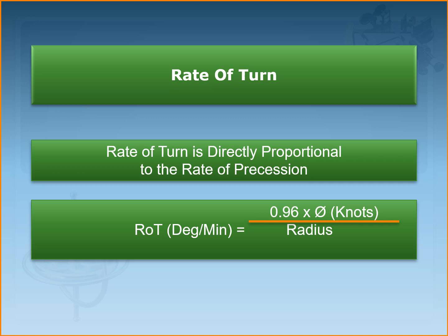This information is very useful when the vessel is maneuvering in narrow channels, or making alterations of broad or large value of courses, or making course alterations between two land masses. Here, knowing the rate of turn in degrees per minute is useful, especially as passage plan information. So you should be calculating this information and putting it down on your passage plans so that you can monitor the vessel's rate of turn when the vessel is making such turns.